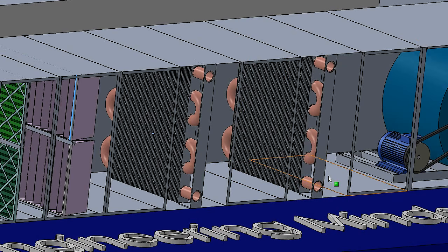And it's good to have this connected so that the coldest water is coming in and the hottest water coming in, entering through the base of the coil and passing through. You'll get much greater efficiency out of this because it's going against the force of gravity, so it gives it a little bit extra time to give off its heat. If you configure it the other way, then it's got that extra momentum of gravity, so it will pass through there and not all of it will give up all of its heat. But this is maybe an advanced step, and we don't need to worry so much about it yet.